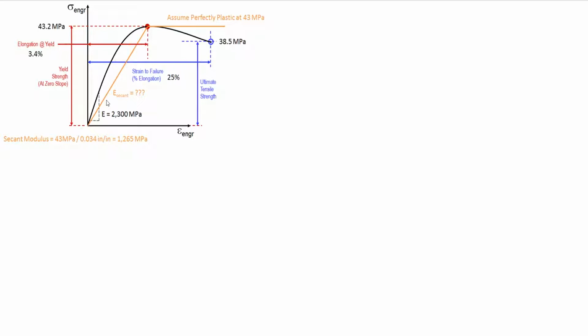While if you had a line that was like this, and it was half, it means it takes half as much stress to get it to strain the same amount. So it's half as stiff. And that's the Young's modulus, flexural modulus, or E, right?